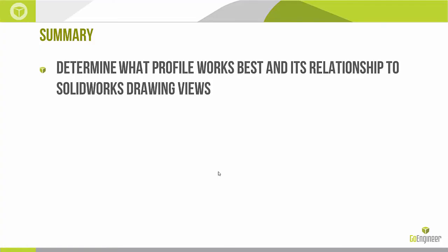One thing that I always like to use as best practice is before starting any project, just determine what profile works best and its relationship to the SOLIDWORKS drawing views. So capturing that profile for your front view, the right side view, maybe the top view, just kind of get a game plan essentially started before putting anything to SOLIDWORKS.